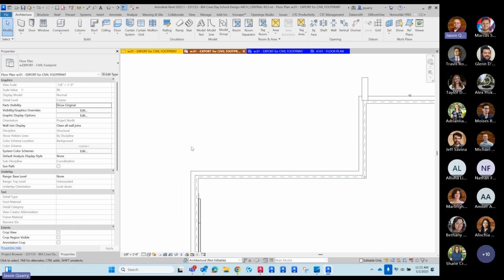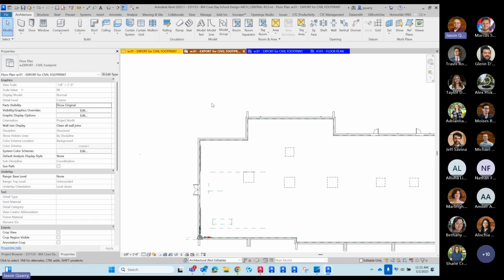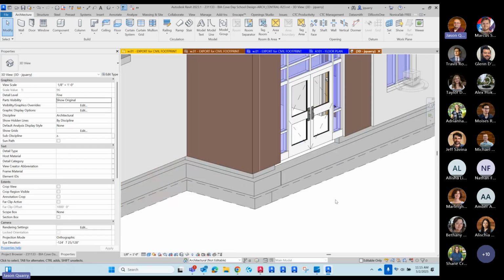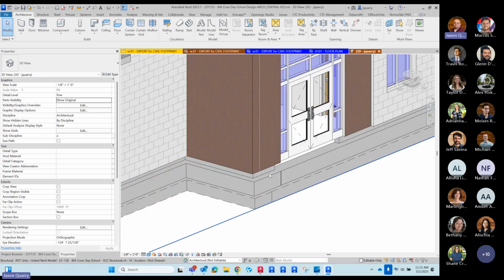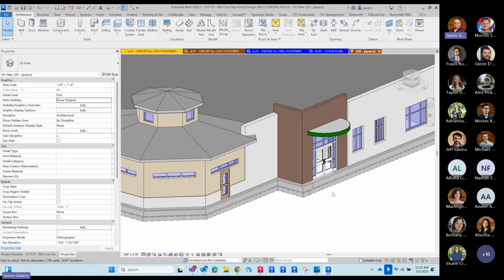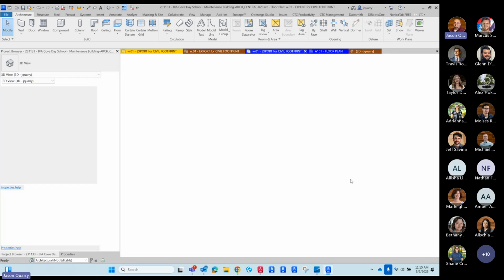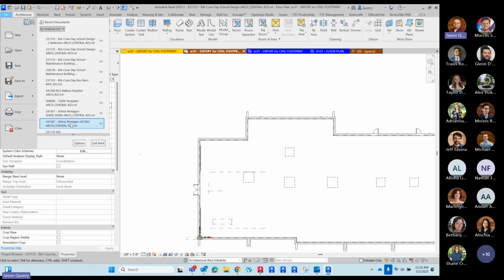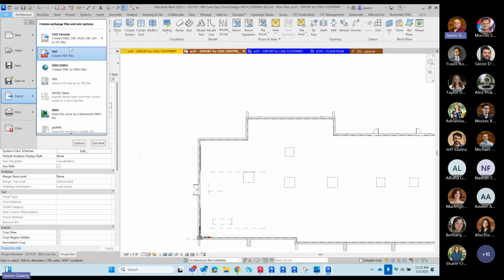The other project that we have here is the school. This is CMU and masonry. This one's pretty straightforward as well, because masonry usually sits on a concrete foundation wall and has a brick ledge. So it's pretty easy to know where that footprint is. It's basically this foundation wall. It's structural in nature, but it's the part that hits the grade and goes through the grade. It's the overall footprint of the building. So that one's pretty easy to identify as well. Then, in this export file, let me just run this one for you so you can see the layering differences.